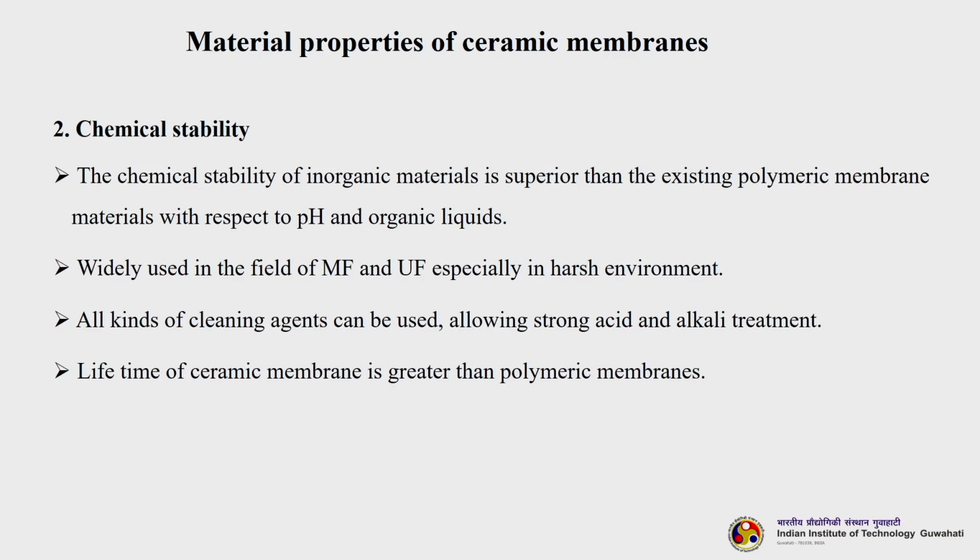Then chemical stability. The chemical stability of inorganic materials is superior to the existing polymeric membranes with respect to pH and organic liquids, widely used in the field of microfiltration and ultrafiltration, especially in harsh environments. So, all kinds of cleaning agents can be used, allowing strong acid and alkali treatment also. However, for cleaning purposes, dilute acids and dilute alkalis are usually used. The lifetime of a ceramic membrane is anyway greater than that of polymeric membranes.